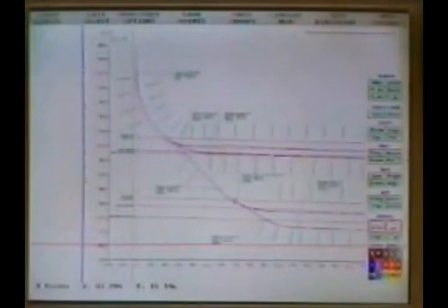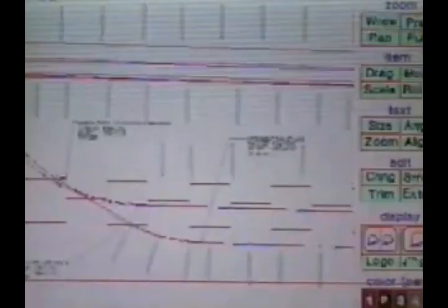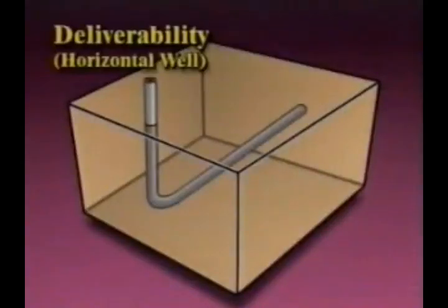As technology has continued to advance, we've seen other areas of application assume similar importance. For example, horizontal drilling, the practice of directing a whole section laterally through the pay zone, is an old concept that came of age during the 1980s. In the right types of reservoirs, horizontal wells are a proven means of increasing formation exposure, raising well deliverability, and reducing development costs.